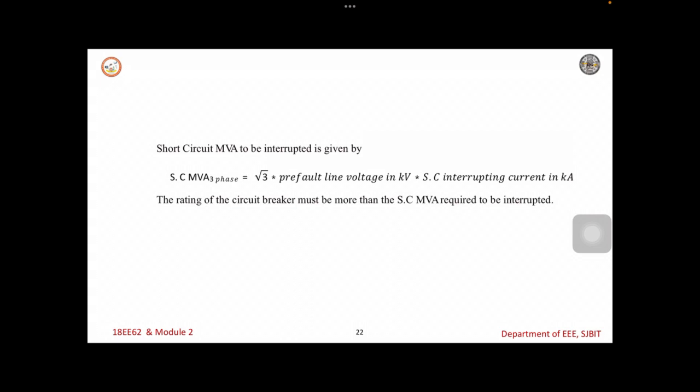So that means we multiply the symmetrical short circuit current by the factor shown. The current that a circuit breaker can interrupt is inversely proportional to the operating voltage over a certain range. Amperes at operating voltage is given by the amperes at rated voltage multiplied by rated voltage divided by operating voltage.